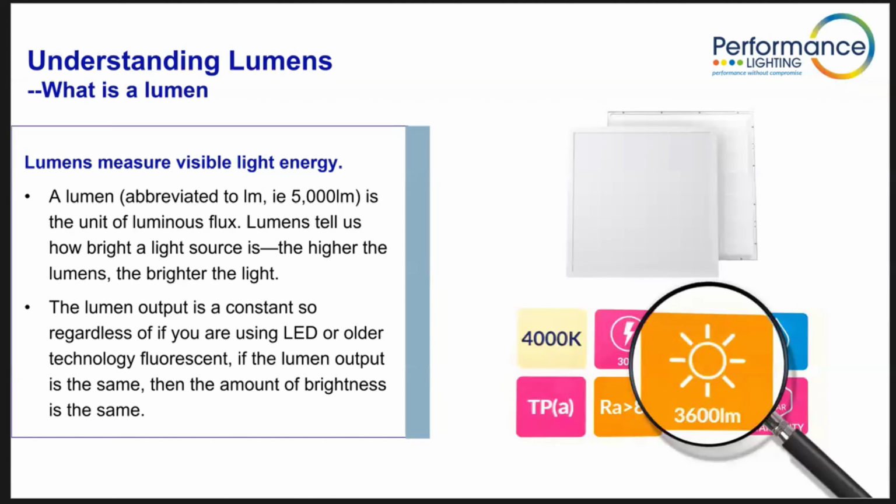What does make a difference is the amount of energy, the number of watts, that's needed to produce that 500 lumens. So, talking about the old stuff, a 60 watt old incandescent light bulb like you used to have at home used to produce around 500 lumens. Whereas nowadays, with the highest performing LEDs, if you were to think about using 60 watts of LED power, you can get in excess of 10,000 lumens from that. So you're getting 20 times more light for the same amount of energy.